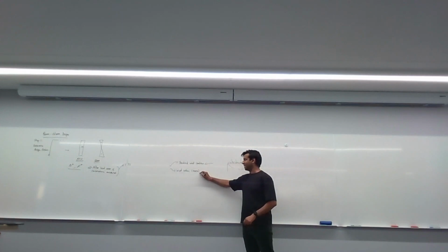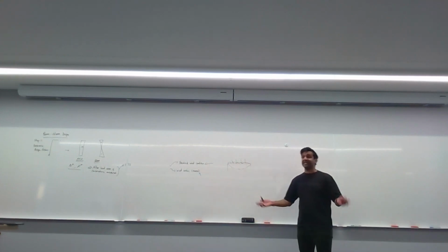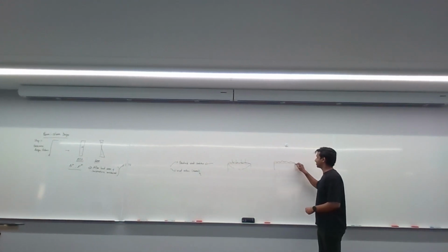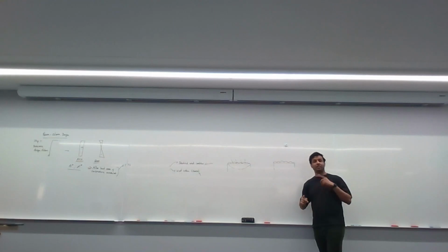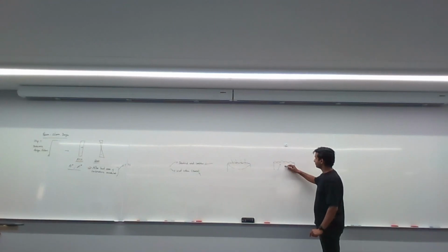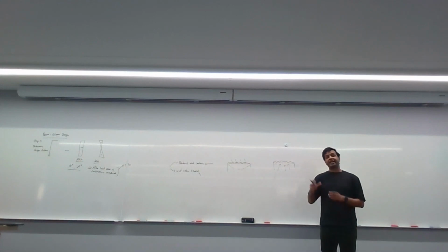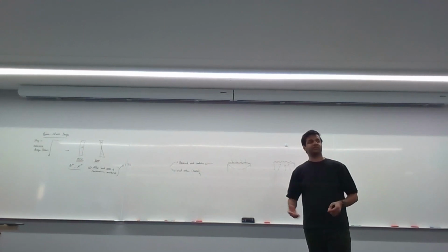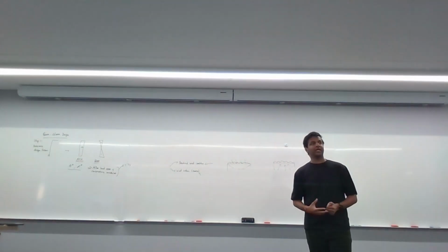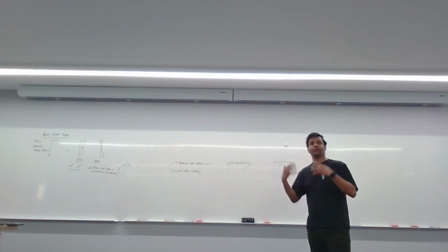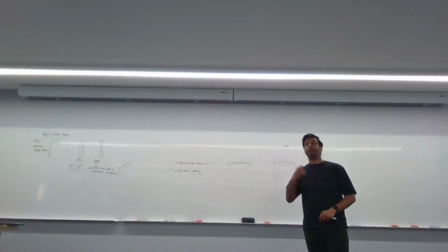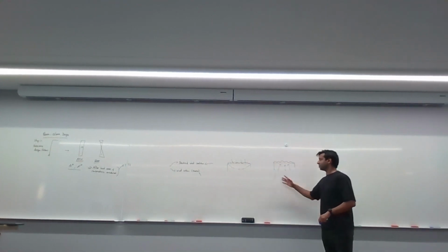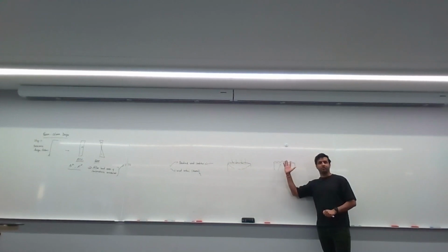Wind action reversal was made for the case where you have wind uplift, which is the other way around. So for example, let's say again you're designing the same roof, but this time around you have your dead loads coming downwards, your live loads are also coming downwards, but your wind is blowing upwards, for example. If that is the case, what you'll generally tend to find is for lightweight structures, and most of the time, when you're dealing with a steel structure, it's usually a lightweight structure, right? Most of the time, when you have wind that's blowing on a steel structure, the wind ends up being one of the most significant loads that it encounters, right? You see, imagine if you have a significant uplift load here.